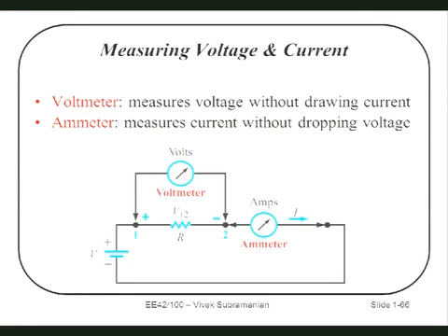That is nominally how you could make a thermometer. But in fact, it turns out that's not exactly what most multimeters use. They use a thermocouple. Okay? And a thermocouple is a device that generates a small voltage difference. And that voltage difference depends on temperature. So it measures voltage directly. Most multimeters do it that way.